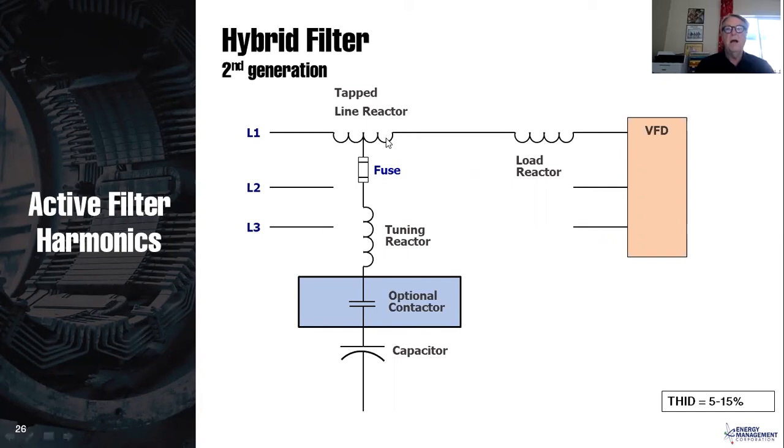And then these are high impedance reactors that tend to just have their DIDT function, preventing rapid change of current. And this particular reactor here is quite a high impedance reactor. I want to mention 2 things. A lot of these, they will claim that you get 5% distortion. On a real system, we tend to see these run 7 or 8% distortion, and that's not bad. I mean, 7 or 8% distortion, I consider clean power, but very seldom will you actually get what's advertised.